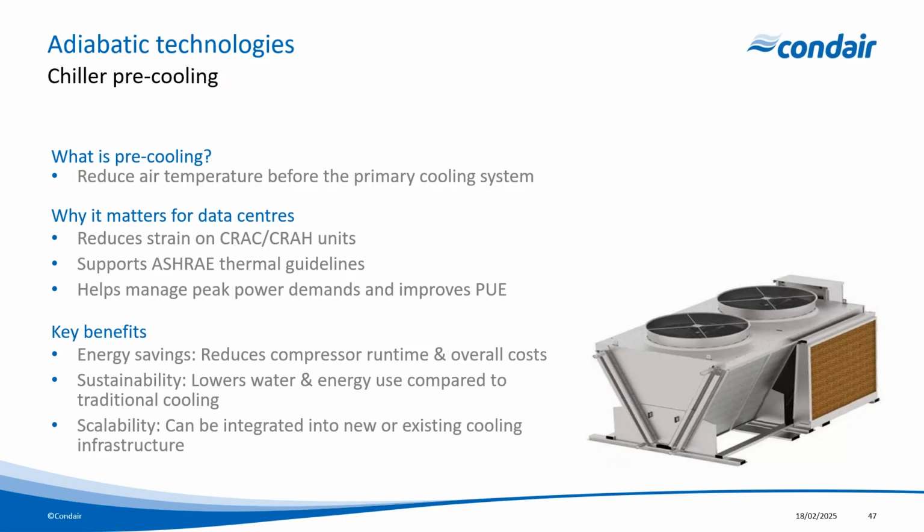Where an evaporative cooling system can help is by cooling the air adiabatically on those extreme days. Your chillers can still operate within their design range and can actually help reduce the overall load on the cooling system, potentially keep you from upsizing your chillers. The most common technologies that we see here are the evaporative media system and some form of atomizing nozzle system. Some manufacturers do offer this as a standard with their packaged chillers or equipment, and there are also products that can be used to retrofit existing installations as well.